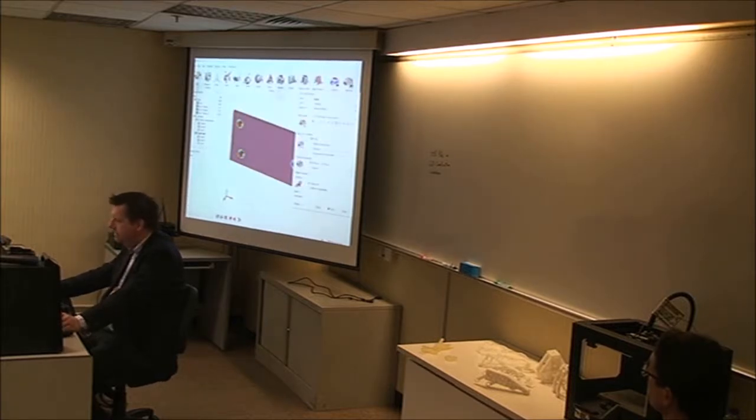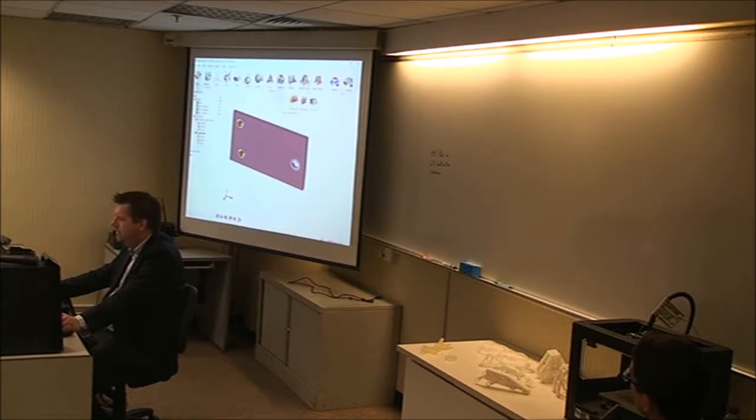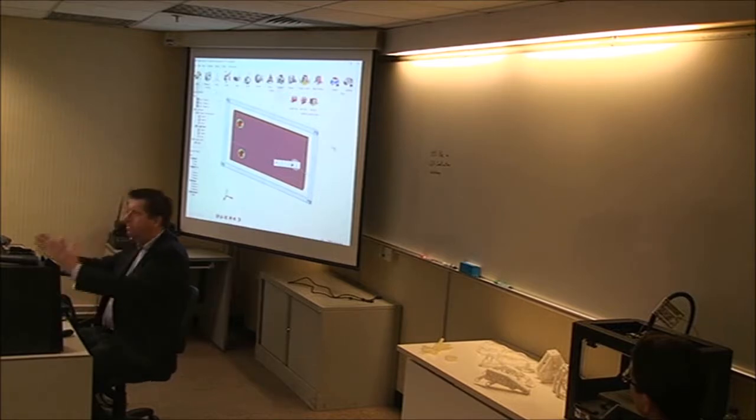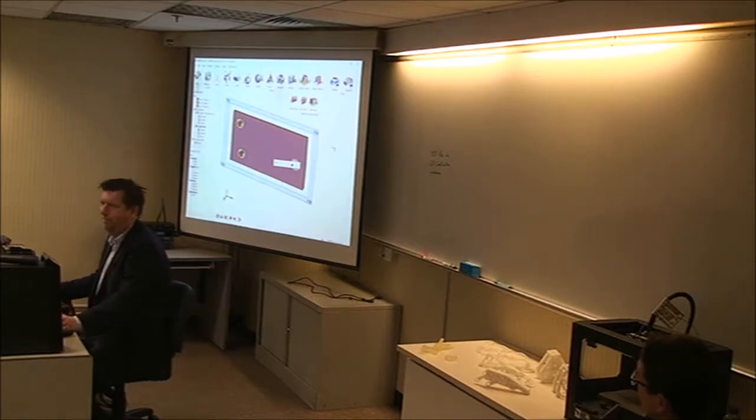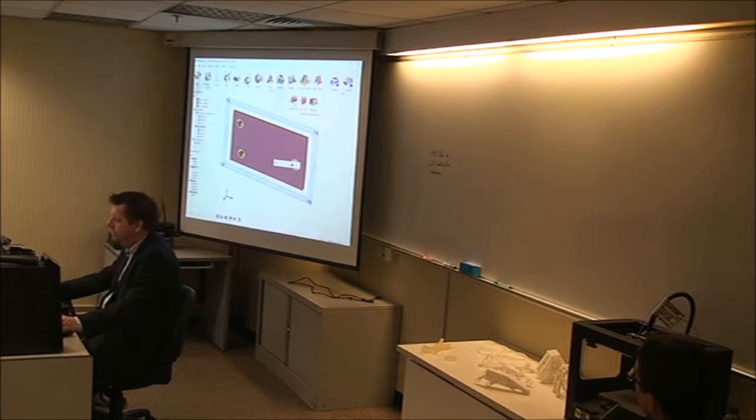Now run an optimization. So we want to do topology. I mentioned topography and gauge. You can combine topography and gauge together, and there's lattice in there now. So we'll just do topology. One thing I didn't do, I wanted to show you the shape controls. So I'll do an extrusion constraint on that guy there. So the result will be a constant section. So it's actually cheating a bit. It makes it much easier for me to do the PolyNURBS on top, so that's why I do it. You can see split draw, single draw, the topography controls, the symmetry controls.